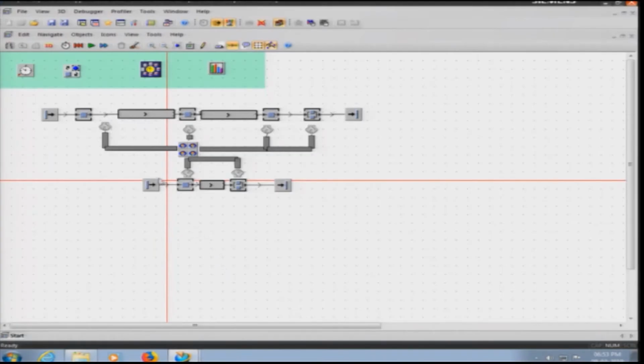Okay, so I have a factory for you. This is a hypothetical factory in which you have different processes. These are single processes: single process 1, single process 2, single process 3, and then we have inspection and packaging. We also have a second line with a single process, and inspection and testing. So what are these processes? The first is selective laser sintering, that is sintering of metal products, or metal additive manufacturing. The second process is CNC, that is post processing, taking place here. After that, this is heat treatment.